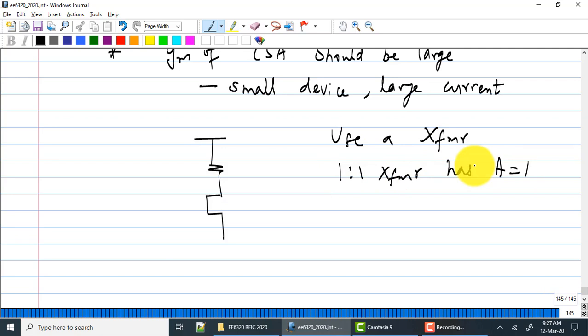Remember, suppose you ignore that 4 RS by RD term. Let's assume that the gain of the circuit is large enough such that that's not an issue. RD is much bigger than RS. Let's just look at the first two. We said that just the common gate LNA had a noise figure of what? 1 plus gamma. And if gamma was, I think we assumed a worst case value of 2, then basically you will get a noise factor of 3, and a noise figure of what?